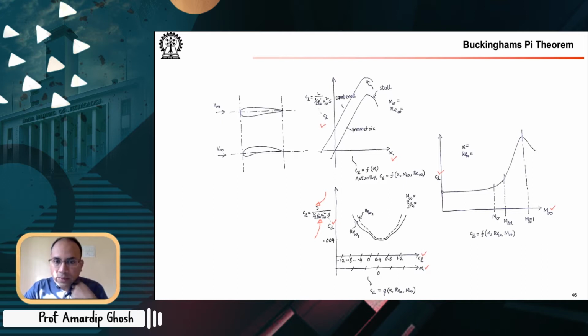And you see that we are saying that at a given Mach number and a given Reynolds number, as you change your angle of attack, or eventually your CL, because CL is a function of alpha, as you see here, your CD has some variation. But interestingly, we are not talking about the dimensional variables against each other. Of course, in experimental work, you might be computing drag versus, say, the free stream velocity, holding some parameters constant.